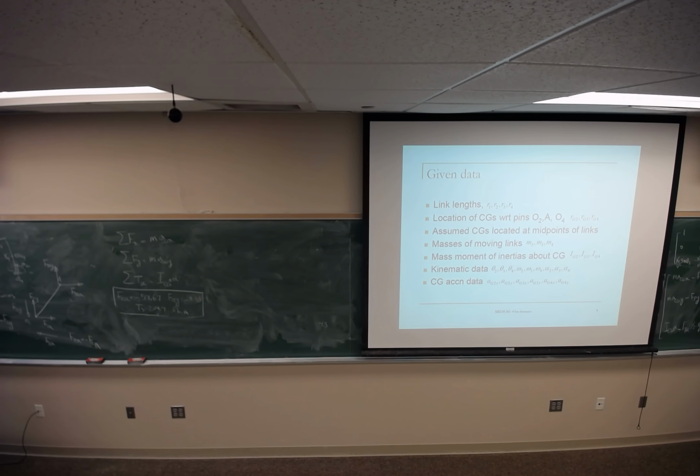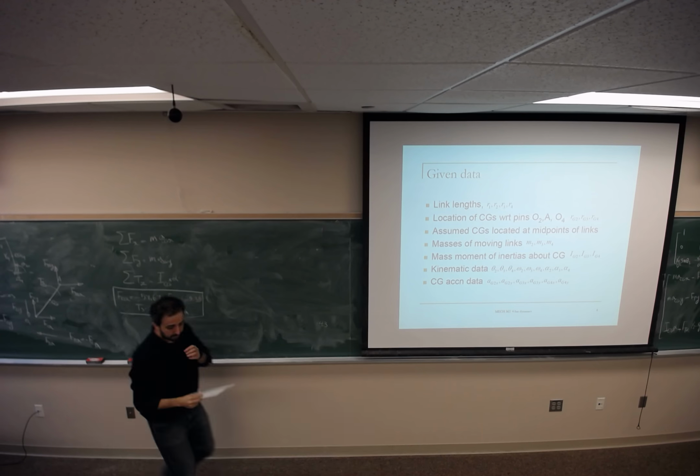These are the only points where I can see that other forces are applied to this link. At point A, what would be the force coming from link 3 applied to link 2 in x direction, and in y direction? The center of gravity is here, and we have one external torque coming from the motor.